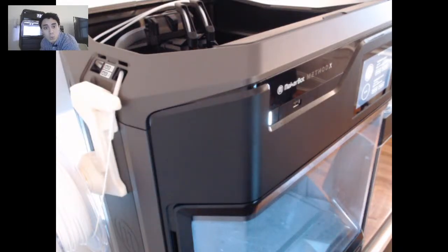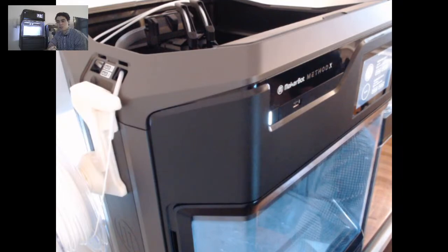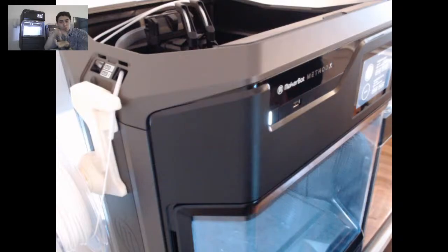But let's see. What's the best application for the Kevlar material? Kevlar, we did a few webinars last year around Kevlar. I would say that generally speaking, you'll want to use it for applications that need to withstand compression forces, not so much for tension, right? We actually did a tension test comparing ABS Kevlar with nylon carbon fiber, and nylon carbon fiber is just much better. However, if you're pressing your parts together, it's going to perform much better for that type of application. If you think about a bench press, or something that needs to withstand compressive forces, that's where Kevlar will actually shine.